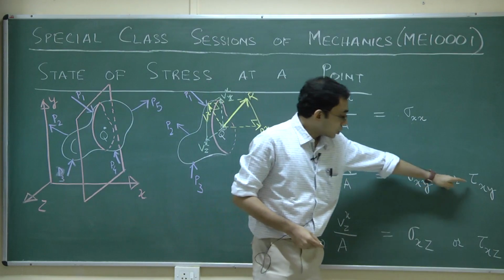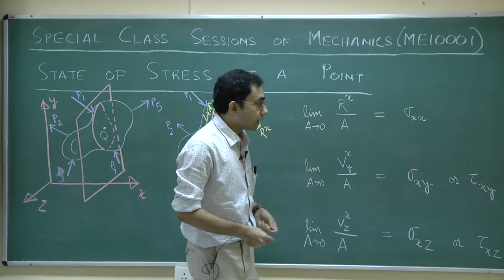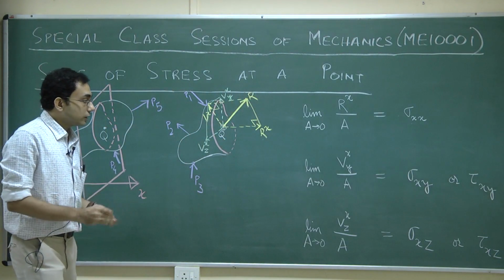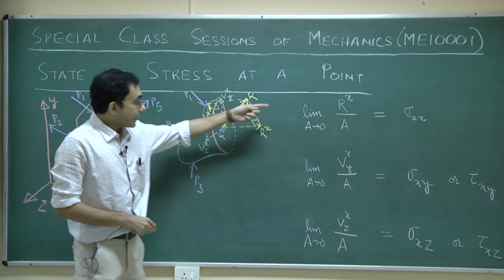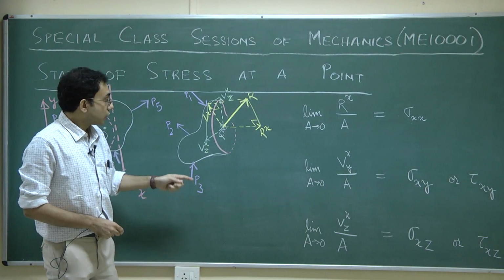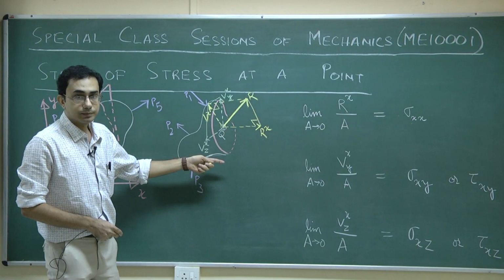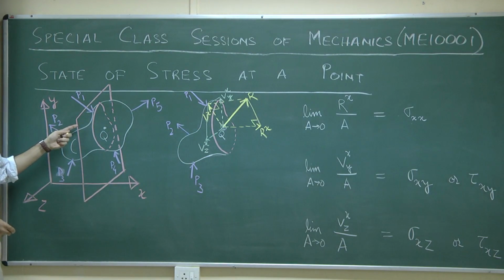These two are referred to as the shear stress components, whereas this is referred to as the normal stress component. Now, at the end of all this discussion, we have to remember that these three definitions only pertain to our particular choice of the plane that we have taken. So this plane, to begin with, was chosen parallel to the YZ plane.